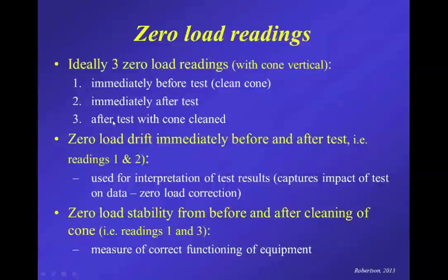But take that reading, and then dismantle the cone, and of course clean the cone out, ready for the next sounding, and then take another set of zero load readings. This third one is often essentially a repeat of one. If you're continually doing CPTs, then you're going to use the cone again, and so you take another zero load reading at the beginning of the next test, which in a way covers that third reading.